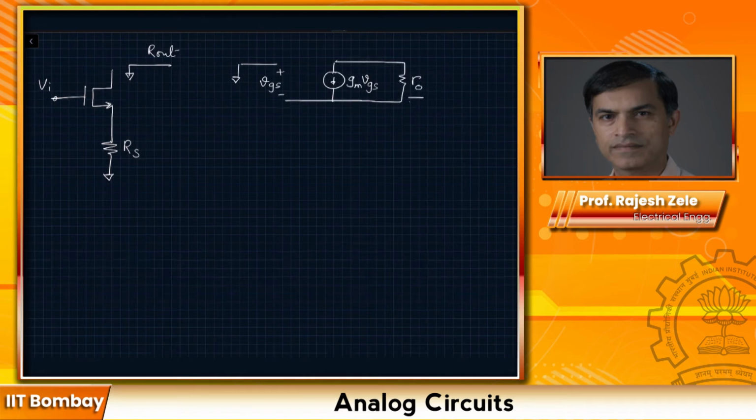In this case, we are looking at the impact of source resistance degeneration on the output resistance of the transistor, and we are trying to figure out the effective output resistance of the stage after adding Rs. So we will have a test voltage source connected at the output, and we are going to measure what is my test current.